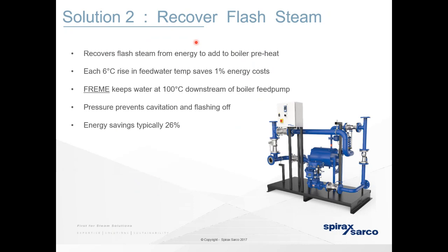It doesn't always have to be as complicated as this. You could re-energize the steam by adding a motive steam connection. Say the steam is coming off at 0.5 bar, but usable pressure is at 5 bar. You could use motive steam to speed it up.